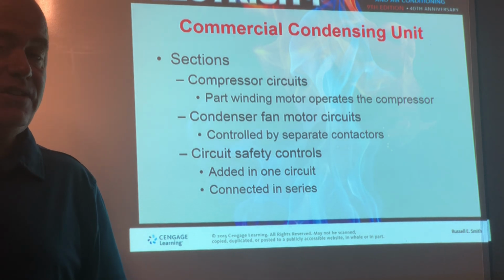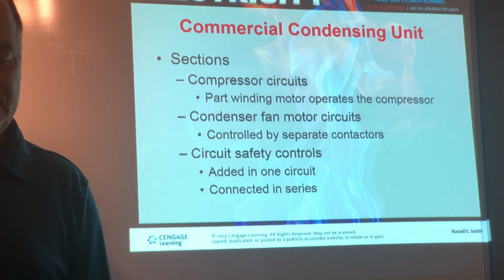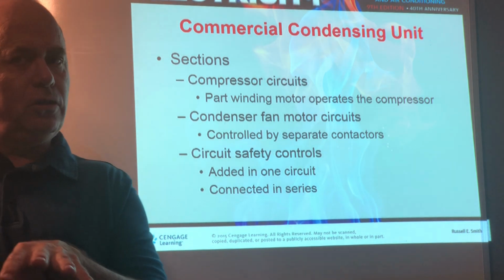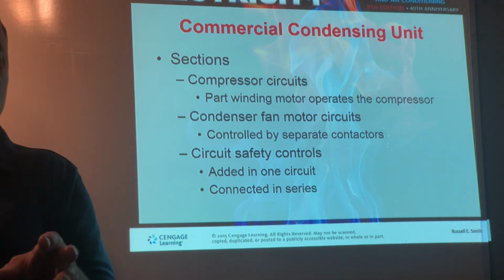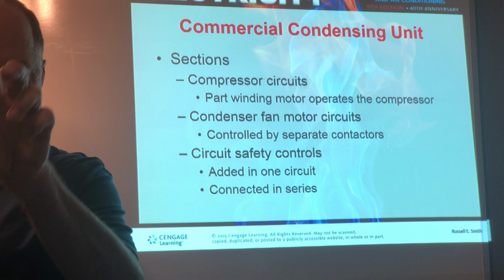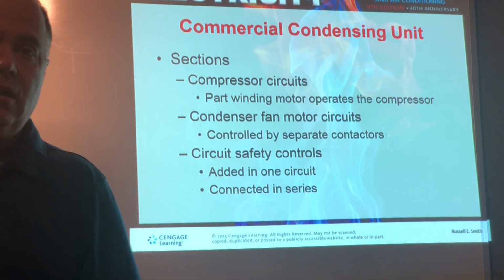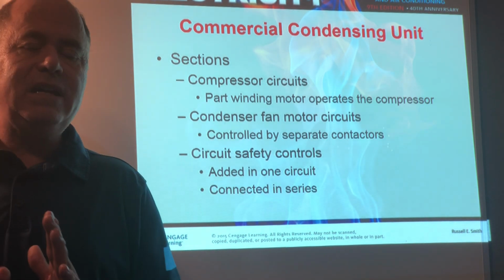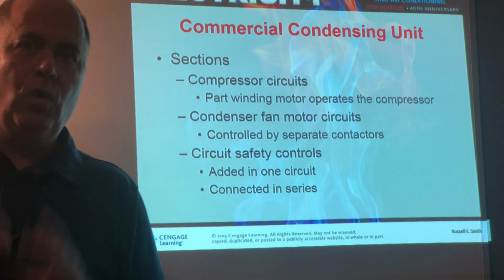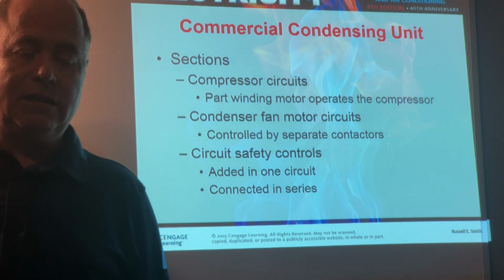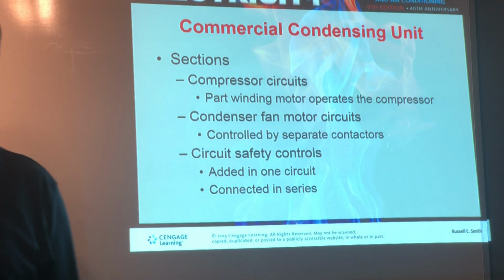Okay, again, a commercial condensing unit. The condensing unit means that the compressor and the condenser are together in one box. And again, in commercial applications, bigger equipment, you always have compressors that have their own contactor. Each condenser fan, or maybe 2 condenser fans, might share a contactor. But you're not going to be finding on larger equipment where compressors and condenser fans share this one little 30 or 40 amp contactor. It doesn't happen because the loads are big enough where they all get their own. Okay.